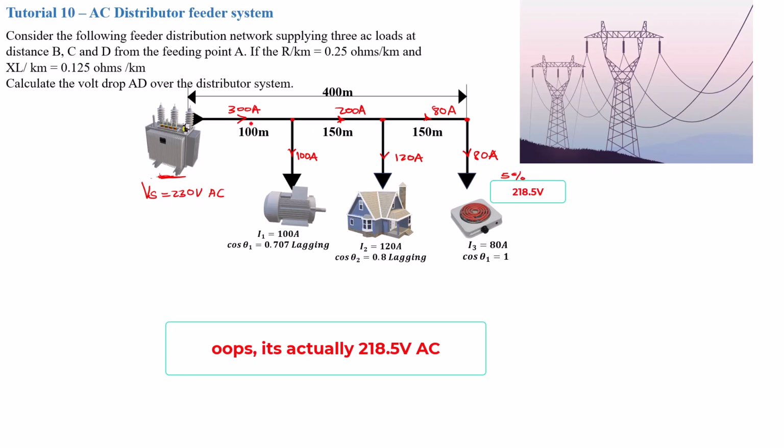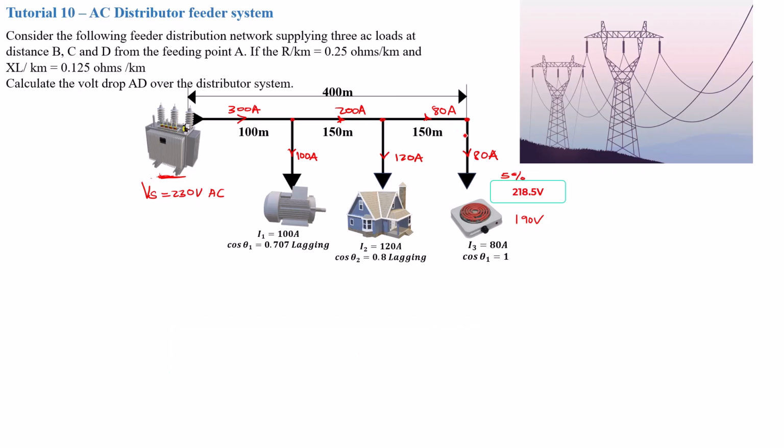But in a situation where the current and cable parameters start to deteriorate, or the current being drawn is getting out of hand, and you have a voltage drop going way above the acceptable 5%, let's say 10%, you've got a situation where you're getting something like 190 volts here. Now this becomes a problem, because many electronic equipment are set to operate at a particular voltage range. So the minute you fall outside that voltage range, your equipment starts to malfunction.